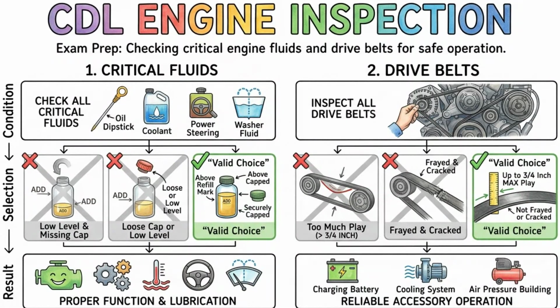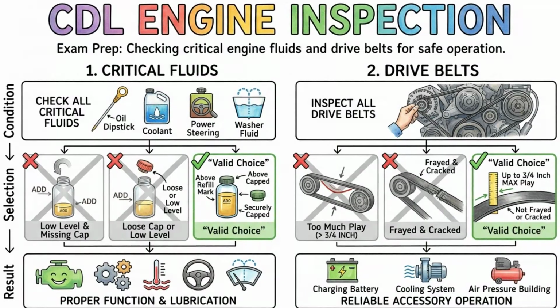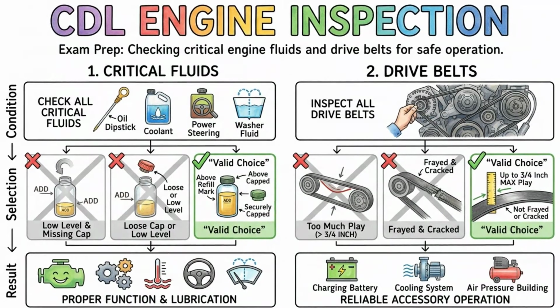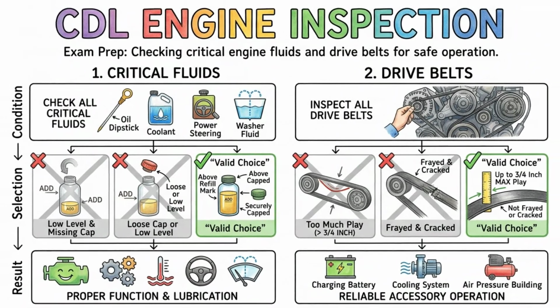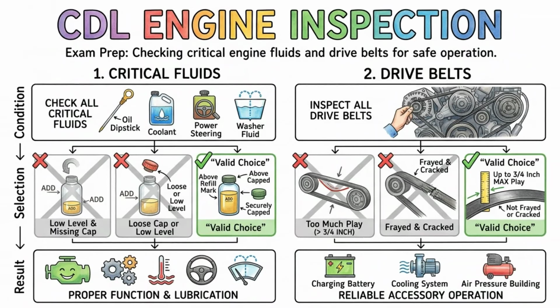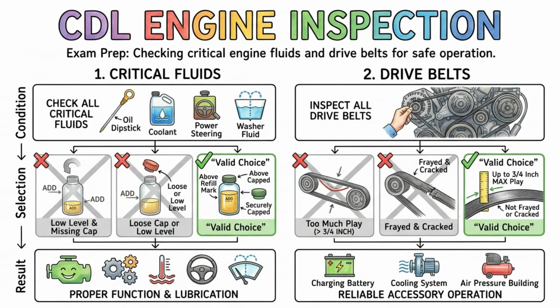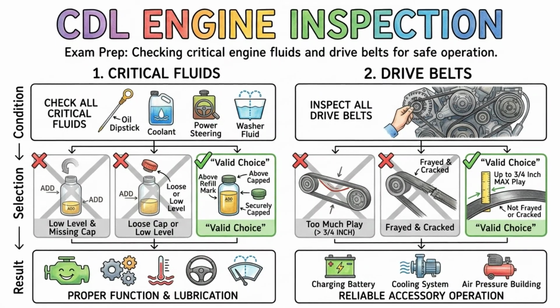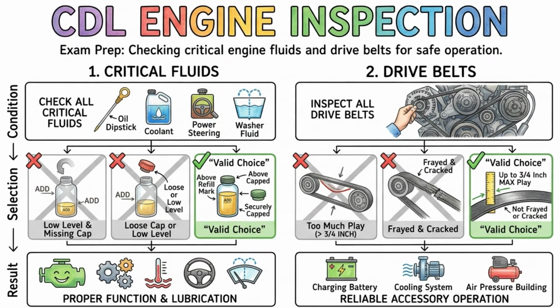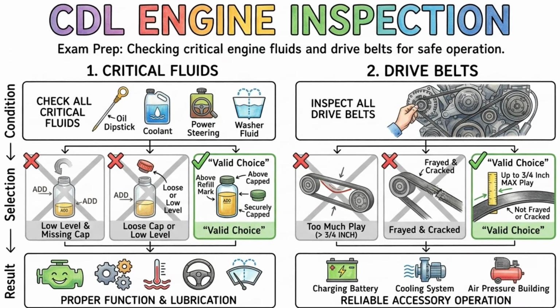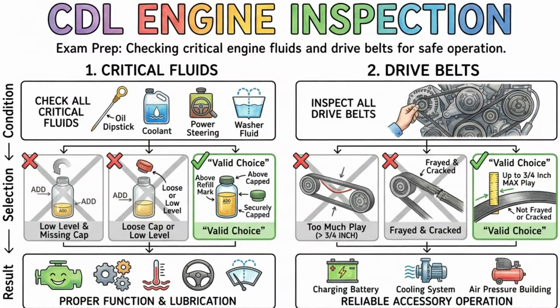While looking ahead is vital, managing the space behind and to the sides of your large vehicle is just as important. You must check your mirrors regularly, ideally every 5 to 8 seconds, to maintain awareness of your surroundings. Commercial vehicles have massive blind spots, often called no zones, where smaller cars can completely disappear from your view. You should constantly monitor these areas and never assume a lane is clear just because you do not see a car in a quick glance. Regular mirror checks help you keep track of vehicles that might be lingering in your blind spots.